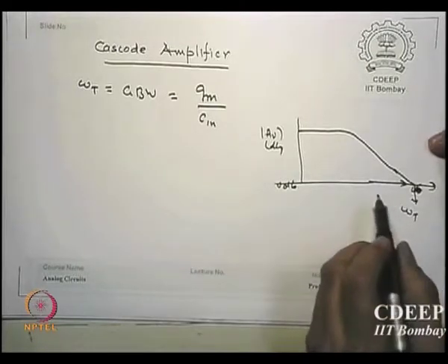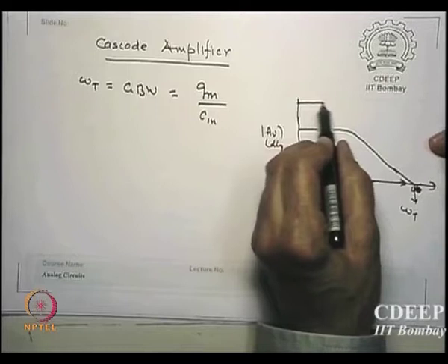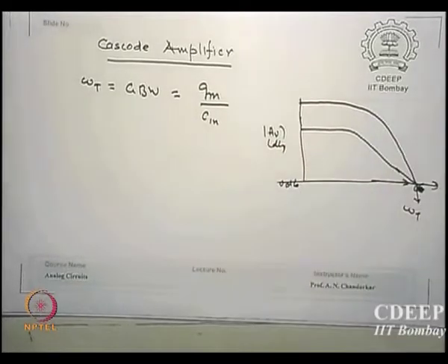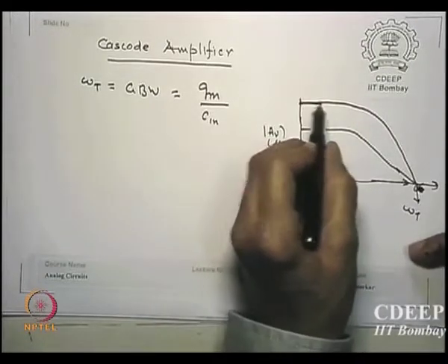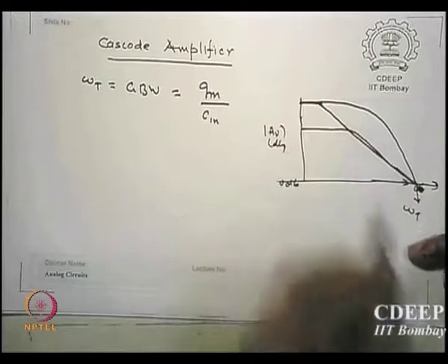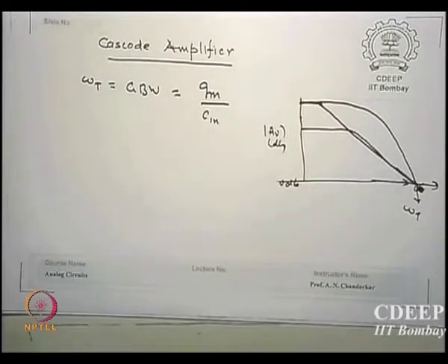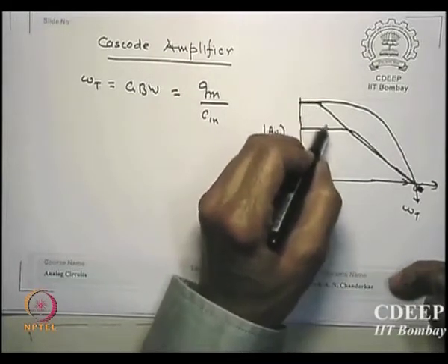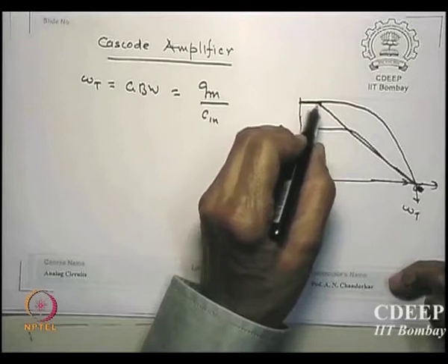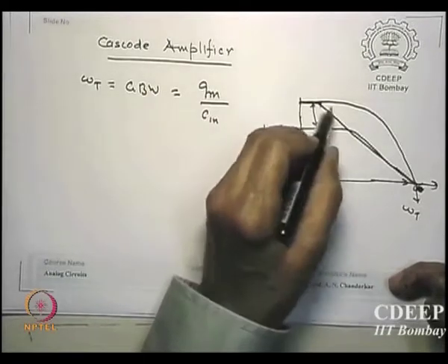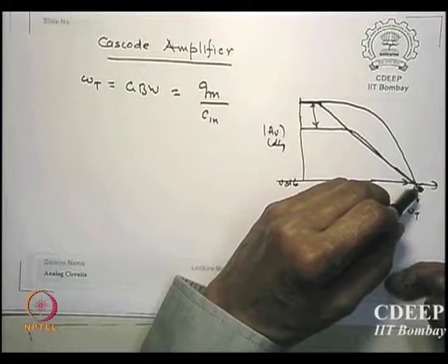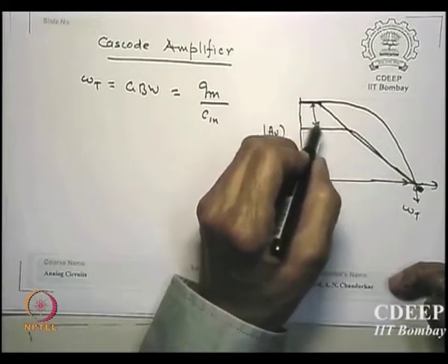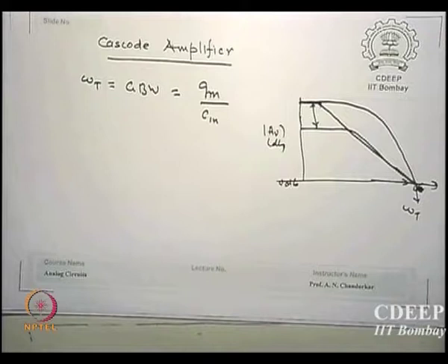What really I want is, or if not this, is that correct? What I am looking for, I may have this frequency where the fall occurs slightly reduced, but the gain is higher, but it should roll down exactly at the same point. Is that correct? So I want, what is it called? Gain boosting. What we did here is gain boosting, but what we did not lose? fT.